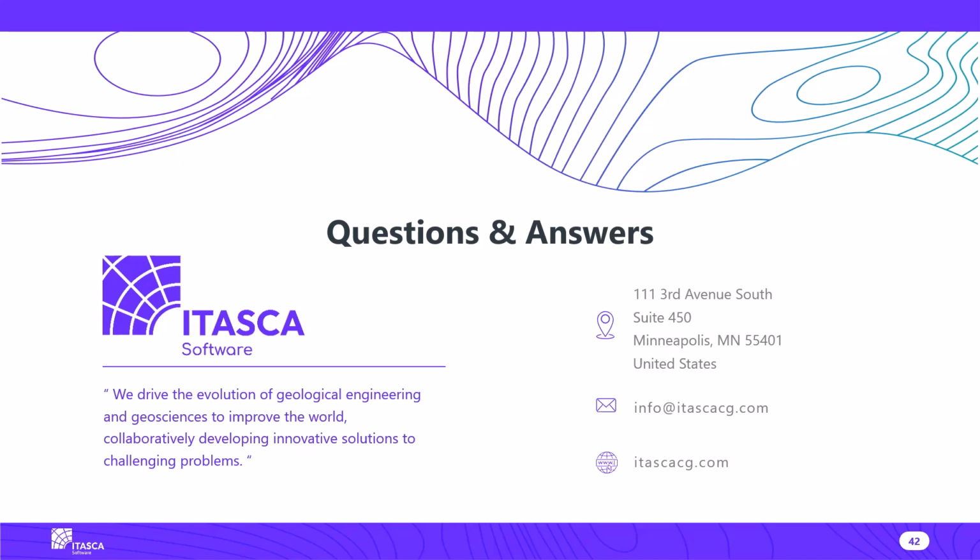Okay. So what you do in this model when you impose the cave, you have the cave geometry. This was done in monthly advances. Initially in your model, you have in situ rock, right? So when you put in the sector where you have the cave geometry, there are 2 crucial things that you should do when modeling. One is to set to 0 the stresses inside the cave. This is very important because this is the mechanism that will cause the redistribution of the stresses around the cave and the development of the abutment in front of the cave.